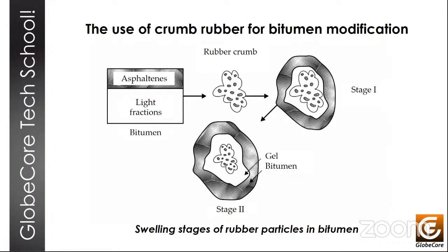Numerous studies and experience of RBB application show that modified binders have higher performance properties in comparison with traditional bitumen. The RBB that we get has higher heat and crack resistance than bitumen obtained from the same raw material, but without the addition of rubber crumb. Next slide, please.